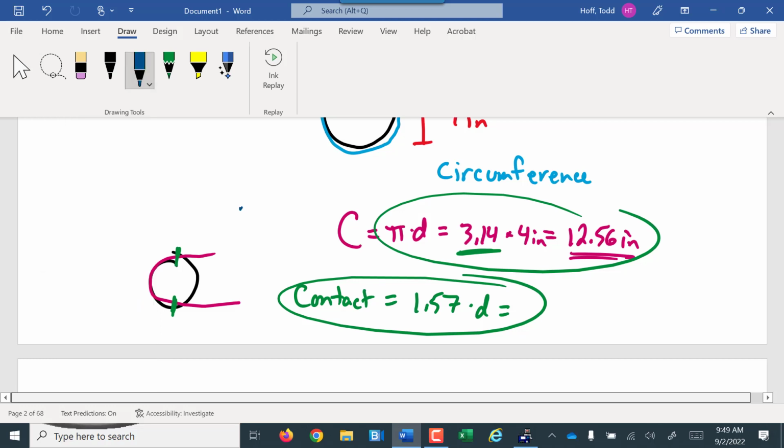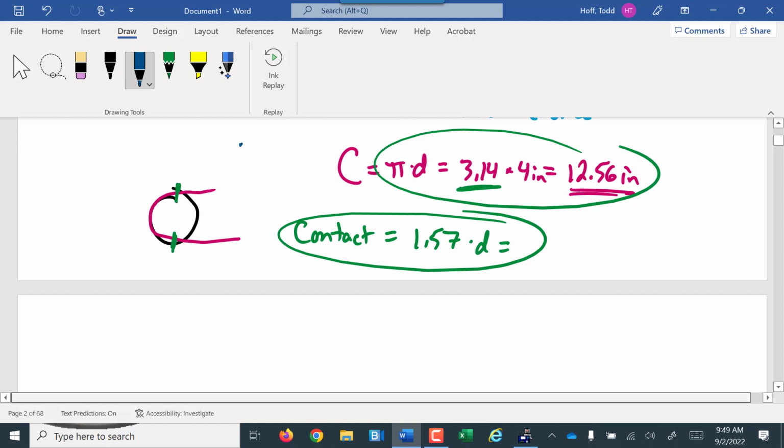Now, this is not a formula that I saw in your book, but when I did work with this stuff, one thing that was important for us was to figure out what size pulley you had to have in a system, because there's friction between the belt and the pulley, and you need a certain amount of force that it needs to be able to handle, so you need a certain amount of surface area to get the appropriate amount of friction between your belt and pulley and a certain amount of tension and whatever. So that surface area helps you figure out if you have enough contact between your belt and pulley, and if you have enough tension on the belt, to get the force you need out of that system.